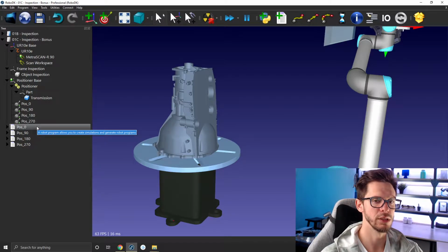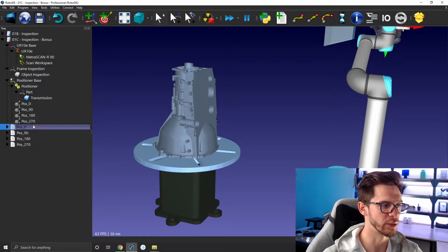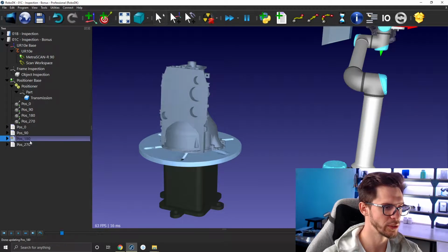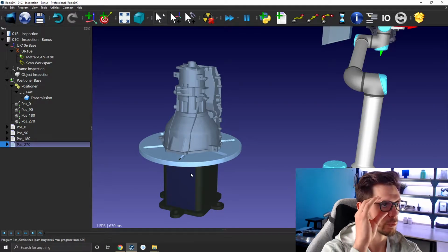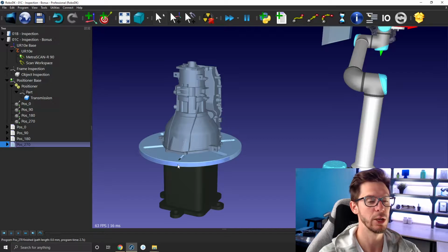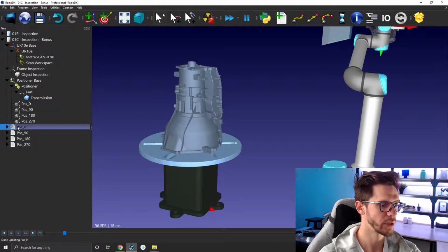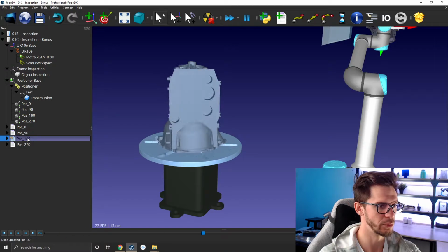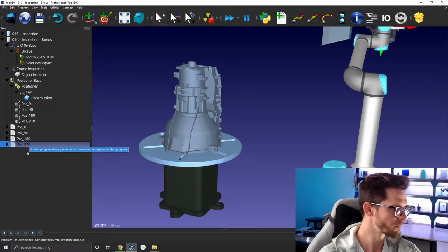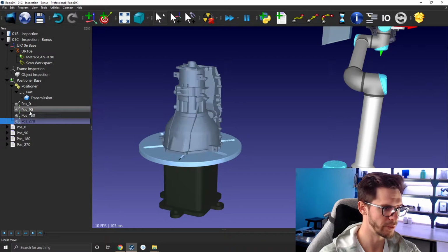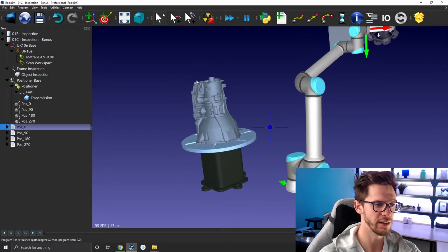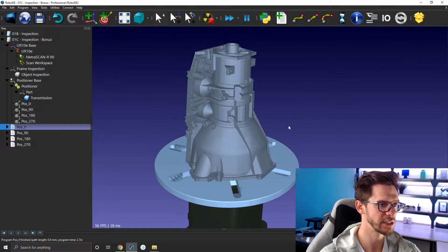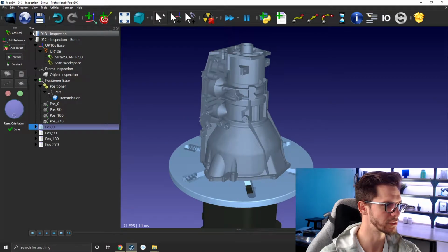And here we have a small external axis that you can use the position to rotate. This is a turntable that I created myself. We can see how to do that in the basic mechanism module, and how to create those motions or rotations with the movement here, or with the position here. But anyway, the point is that you can use that to create the inspection process. Two little things real quick that are super interesting. If you go to program, teach target on surface, okay,